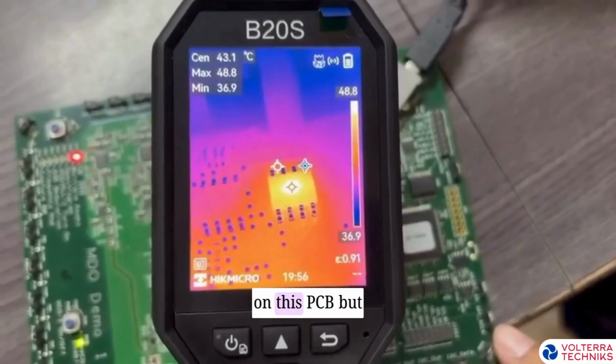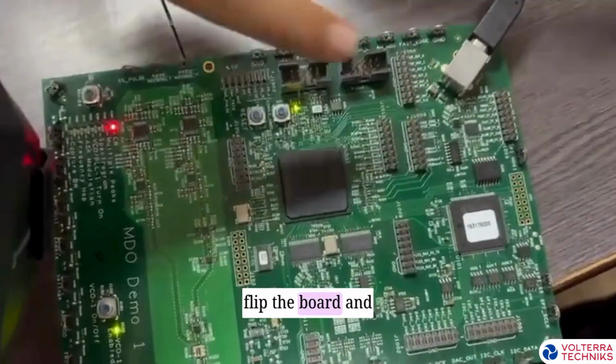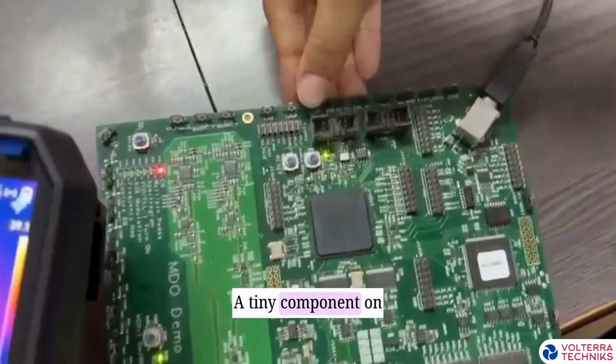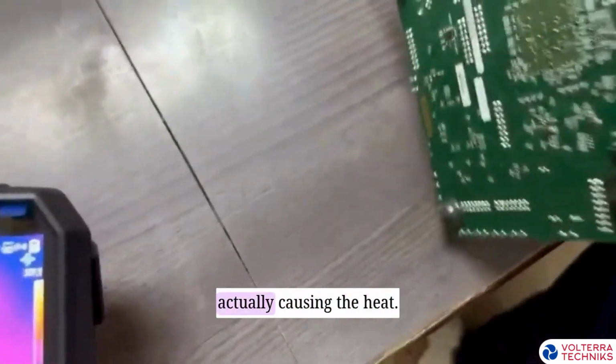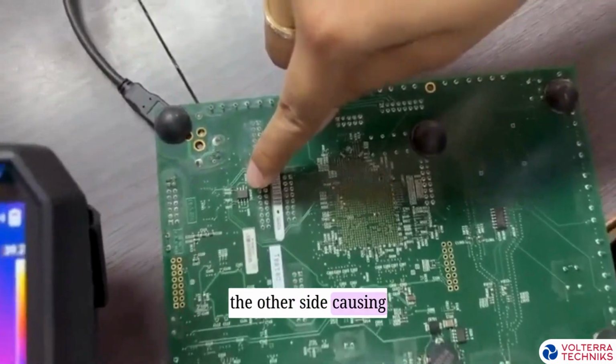We detected heating on this PCB, but visually there's nothing obvious on this side. So we flipped the board and look what we found. A tiny component on the other side was actually causing the heat. So we found the source, a tiny component on the other side causing the heat.